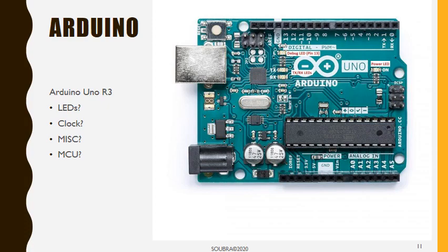Perfect. So here, please take notes, of course. Usually boards have external clocks on them. What for? To synchronize the timing of every module that might be on the board. All right? The type of this particular clock that you're seeing here, we say that it's crystal based. Anyone has an idea what that is and why would we have a crystal based clock?